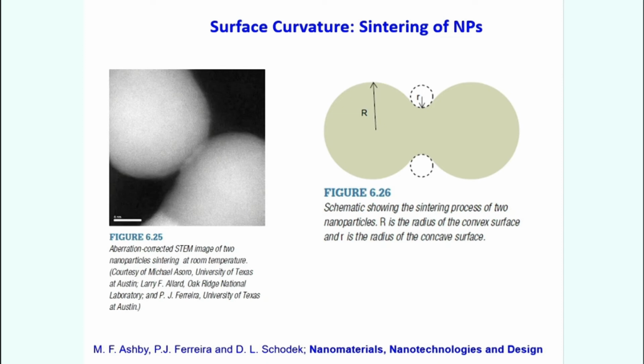Well, let us look at it. See, that is what I told you, this is a curvature, just now I told. Convex, concave, convex. Because of vacancy differences between this point and this point, the vacancies will move, there is a concentration difference that will lead to migration of vacancies, and in the opposite direction mass will move, right. So, as the mass moves, this particle will join one with the other. More and more mass will move from this top region to the bottom, and this will lead to an increase of this particle size. That is what happens when something sinters, you can see that, okay.